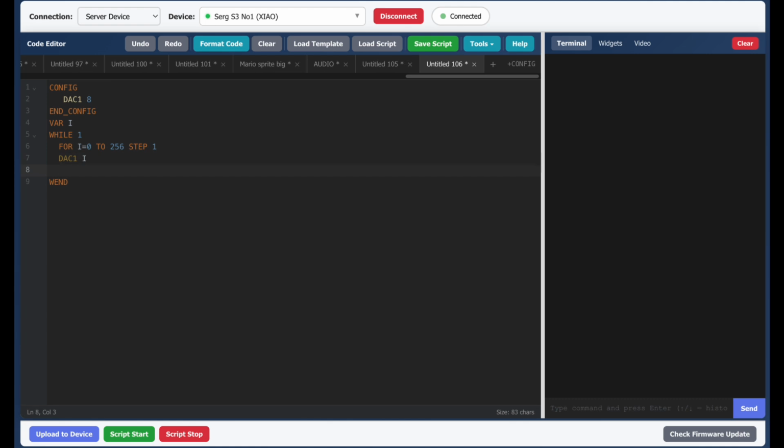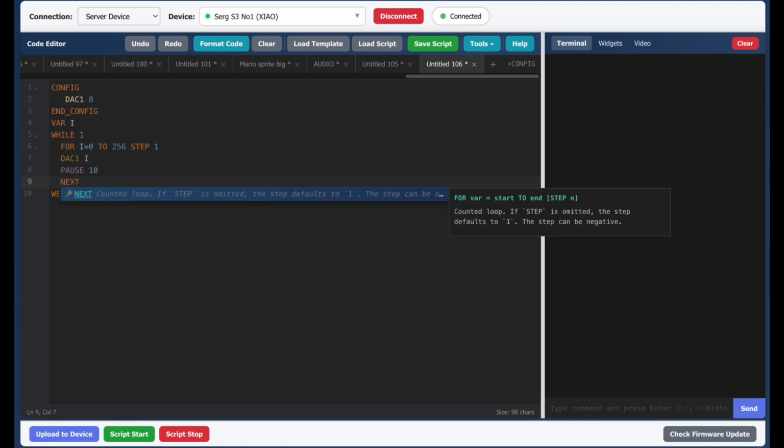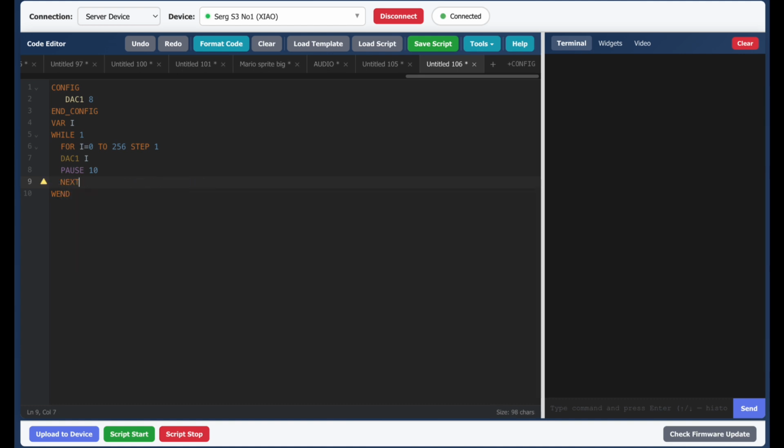Instead, they use a sigma delta modulator. It generates high-frequency pulses whose average value produces the desired voltage level. For most use cases, controlling LED brightness or powering a low-current load, this works perfectly fine. But if you need a clean analog signal, you'll need an external RC filter on the output.